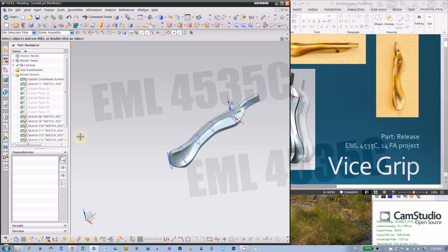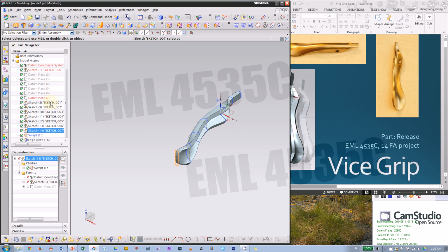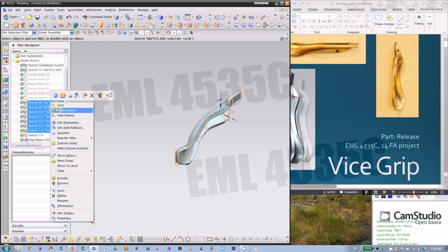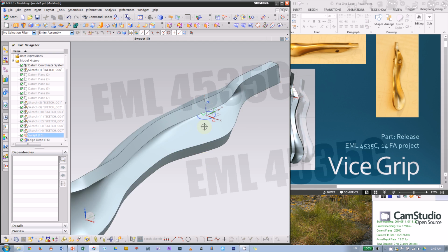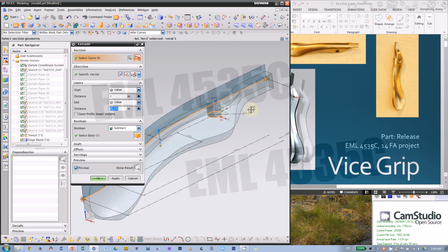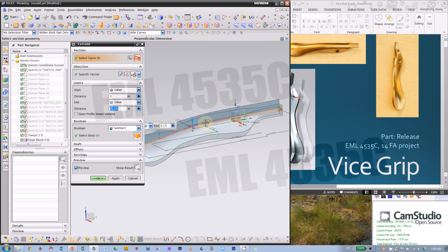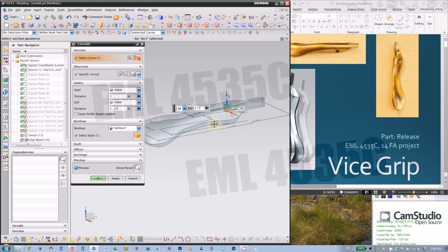that'll be fine. Okay, so I don't want to see so many cross sections on my solid, so I can just shift and click, like Windows multi-select, then hide. Alright, now the next, or the last step, is to make this hole. Simply use extrude, pick this arc. I have this on the region boundary curves, so that means area. It works well here. You can also use inferred. It's probably going to extrude that guide curve, so you don't want that. You want connected curve or single curve just for this little circle.